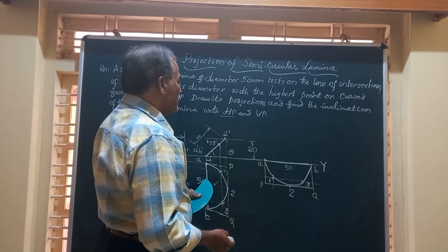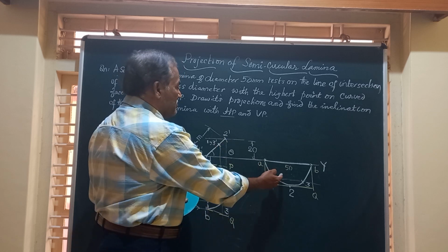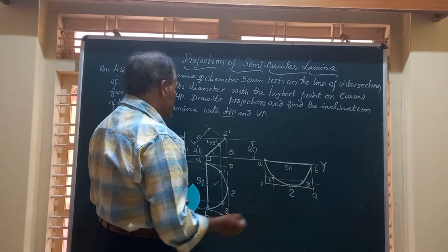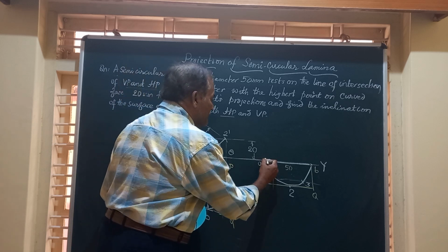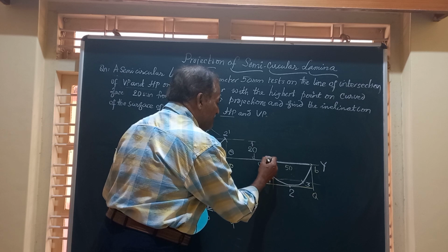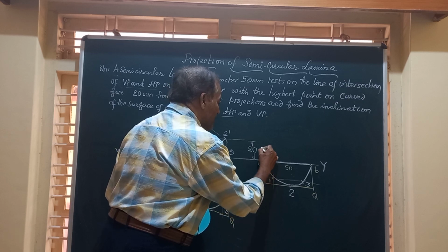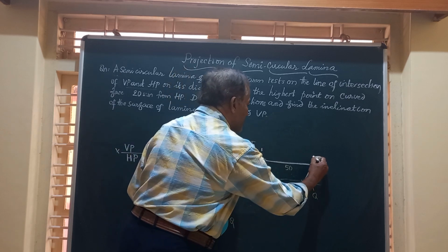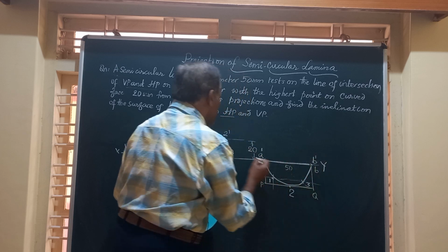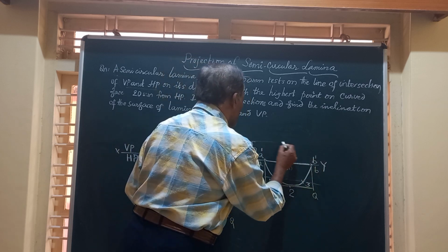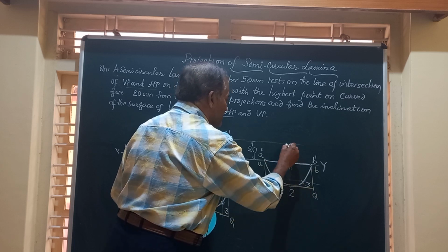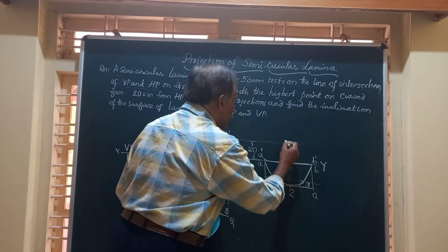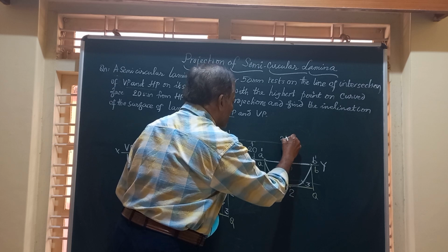Now friends, finally obtain the front view corresponding to this. The procedure is very simple. So draw a horizontal from A dash, and a vertical from here, they meet here. We will call this point A dash, and this is going to become point B dash. Then the highest point is 2. That comes exactly in between this AB. So probably somewhere here. This is going to be point 2 dash.